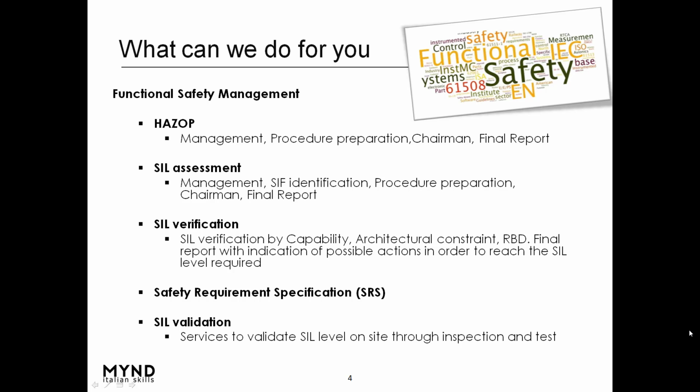A very important aspect not to be overlooked is that of the safety requirement specification, because with the new revision of the IEC 61511 standard, SRS has now become a normative component. This means that to be compliant with the standard itself, it is necessary to develop the SRS. During our course, a special section is reserved, listing all the necessary items to be included in the SRS.